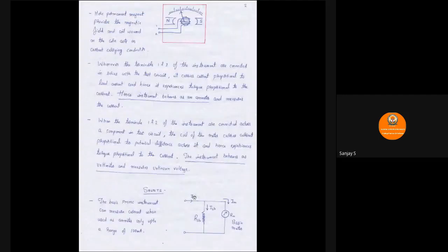From this circuit you can see R shunt and basic meter are connected in parallel. So the voltage happens to be the same in parallel. The voltage across the shunt is I shunt R shunt. The voltage across the basic meter is IM into RM. That being the case, I shunt R shunt will be equal to IM into RM. From this we can write the expression for R shunt, which is equal to IM RM divided by I shunt. And this I shunt can also be expressed in terms of the main current, which is I minus IM, because of KCL. So this can finally be written as R shunt equals IM RM divided by I minus IM,